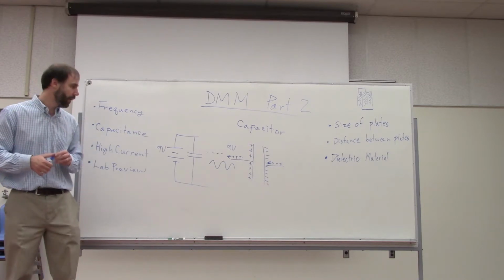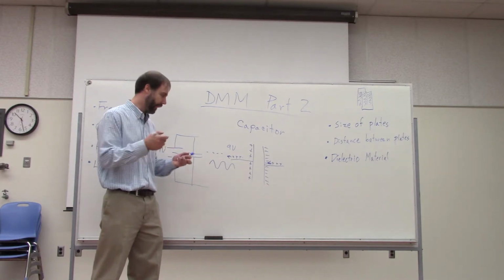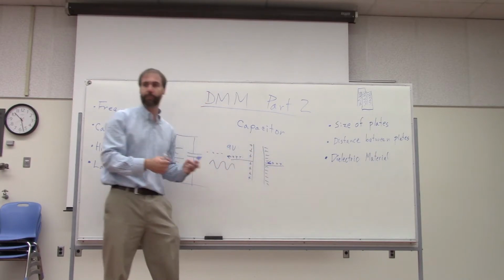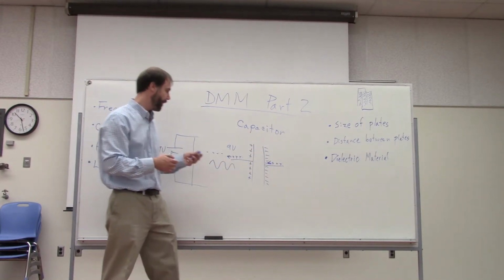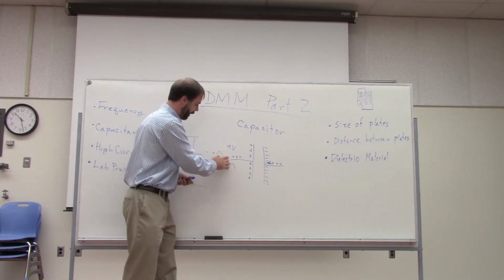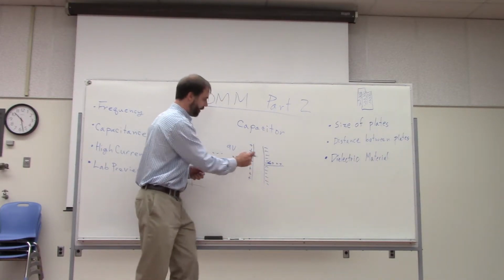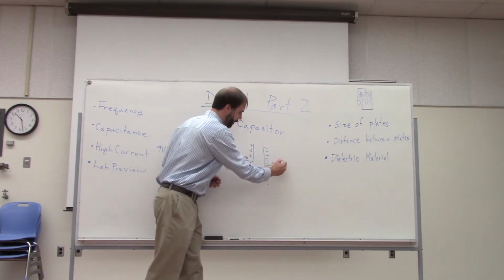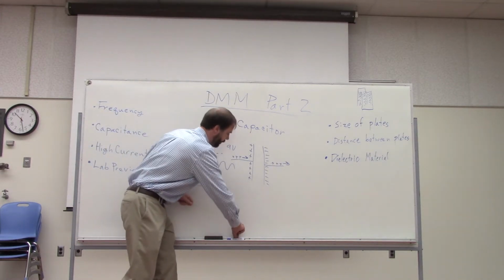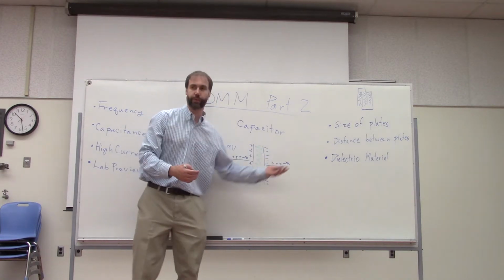That makes sense. Yeah, and another thing I should point out is that just like with the diaphragm, nothing actually passes. The electricity does not actually pass through the capacitor. It just appears to be. So when you push charges on from the left, for instance, that pushes the charges off from the right-hand side, but they are different charges, right? So it might be the same amount of charge. So you get 5 electrons on the left, you lose 5 electrons from the right.